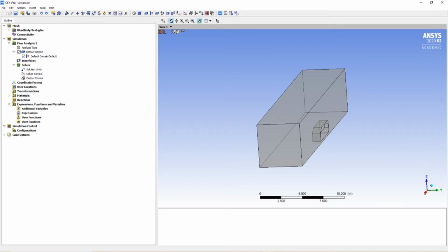Okay, so basically the flow of air in the domain is expected to be turbulent. So the shear stress transport, or the SST model for short, with automatic wall function, can be used and will be used because it is highly accurate in predicting flow separation. Okay, so to take advantage of the SST model, the boundary layer should be resolved with at least 10 mesh nodes, so the boundary layer near the walls should have at least 10 nodes.